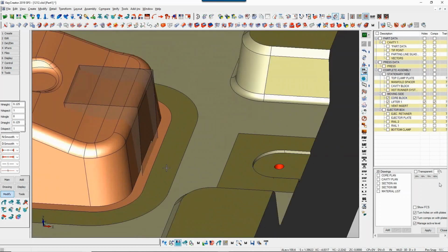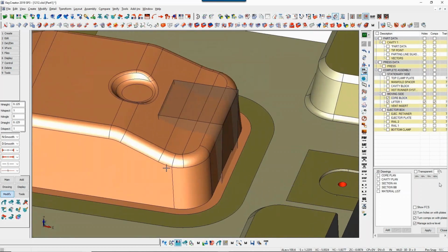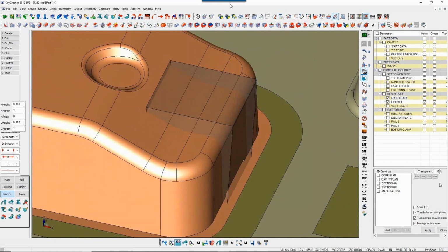So very easy to do when you're modeling in XMD. Once again, it makes things very easy for your shop floor. They can create macros based on these RGB values, and they can really speed up things like roughing and finishing and semi-finishing, and all that stuff can be drastically sped up programming time-wise by utilizing these capabilities.